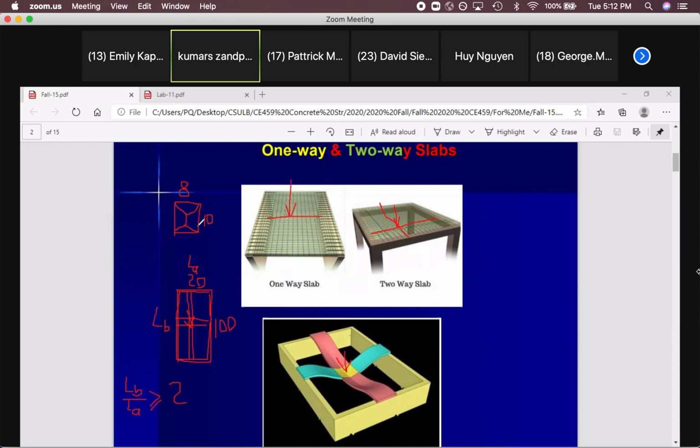So if you have two-way slabs, in your structure, the loading on this beam is not uniform load. If you have a slab, because it's two-way slab, you should consider trapezoid load on this beam, triangular load on the beam perpendicular to other side. So the load is not uniform, just rectangular uniform. It's trapezoid and rectangular for two-way slab.